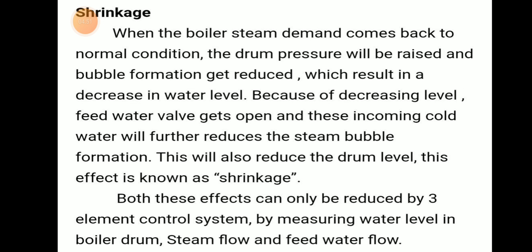Shrinkage means when the boiler steam demand comes back to normal condition. When the steam demand is normal, the drum pressure will be raised and bubble formation is reduced. This is the exact opposite of swelling. The bubbles were applying pressure on the water, so now the water level will decrease.